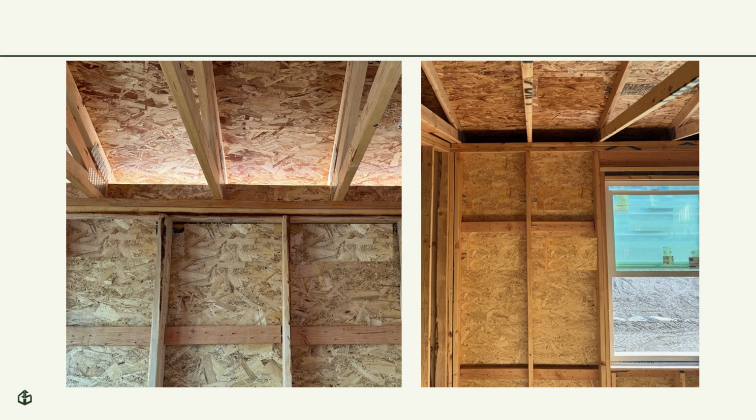In these pictures, the blocking may not have been required for rotation of the members, but as the panels below have horizontal blocking, it is likely that they are brace wall panels and therefore blocking between the trusses is required above them.